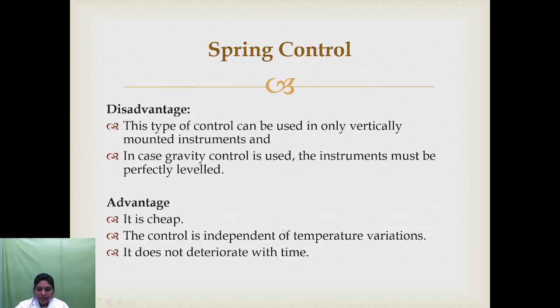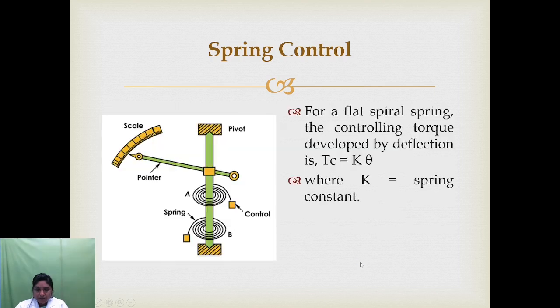At equilibrium, the controlling torque will be equal to the deflecting torque. The deflecting torque is proportional to the operating current.